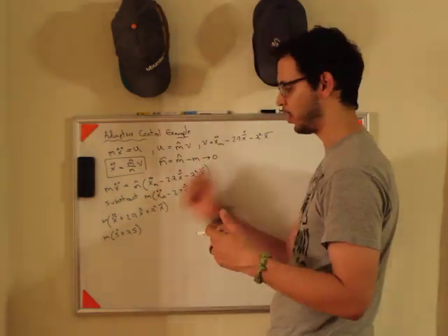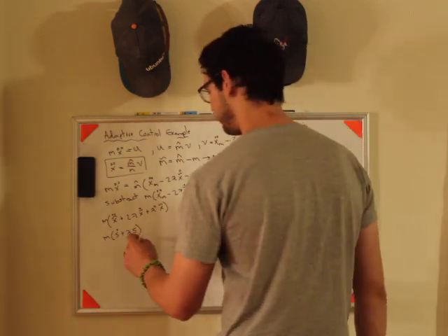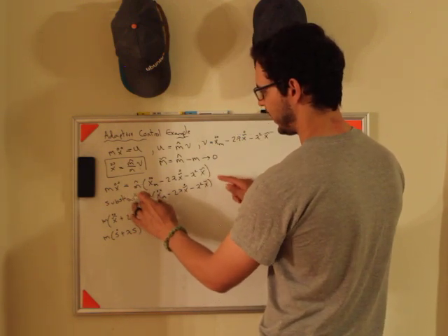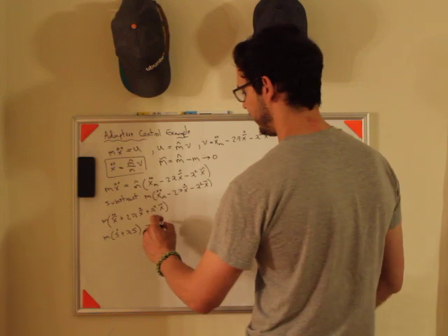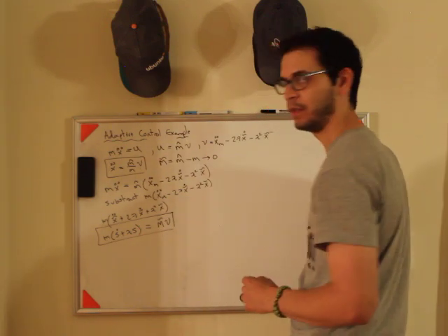This is m times (s plus lambda) s. I've already shown that in the previous part, so if you don't recall, rewind it. This is that first order transfer function here. Okay. This is going to equal, well, what? This minus this. These are the exact same things. And m hat minus m is just m tilde. So I'm just going to get m tilde v. And these are my closed loop dynamics.